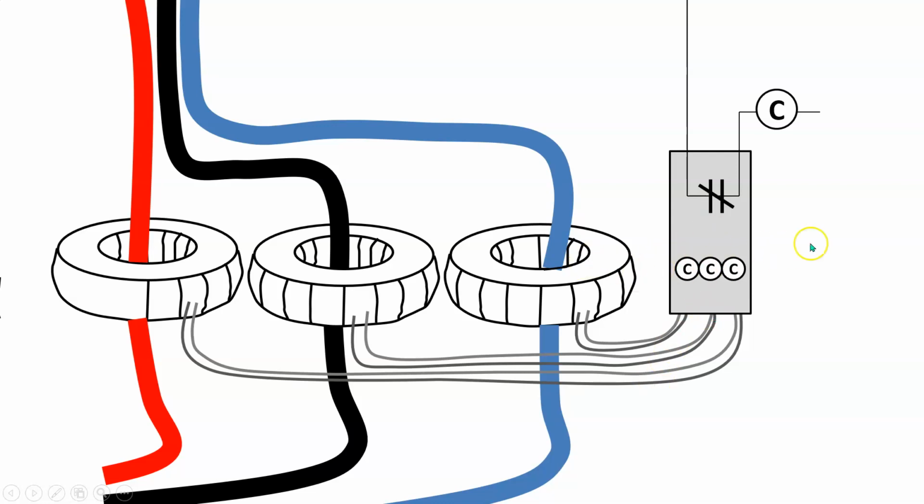It's electronically done, so if these coils here start to sense way too much magnetic field, based on too much current going through these conductors, it's going to electronically cut out and open up these contacts going to the coil. Again, opening the armature up, contacts open, motor turns off.